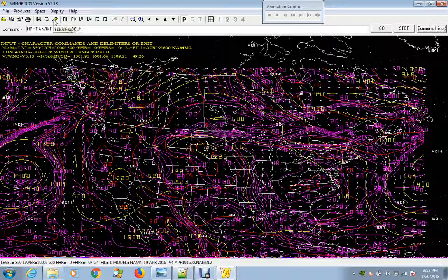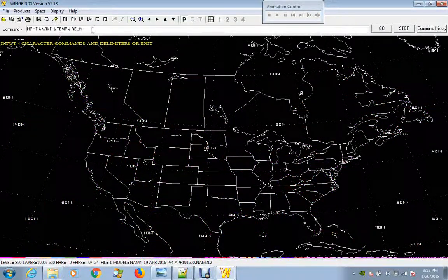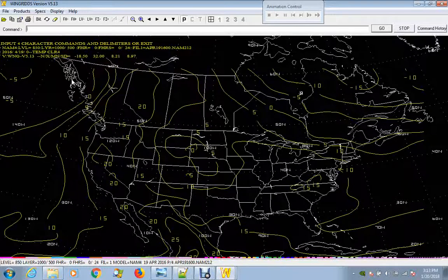You can override that. Let's erase that. And say we want to show the temperature, let's say, in color number 4. So we go TEMPCLR4. That will force color 4 to be evaluated for the temperature. And there we see temperature is being shown with the fourth color.